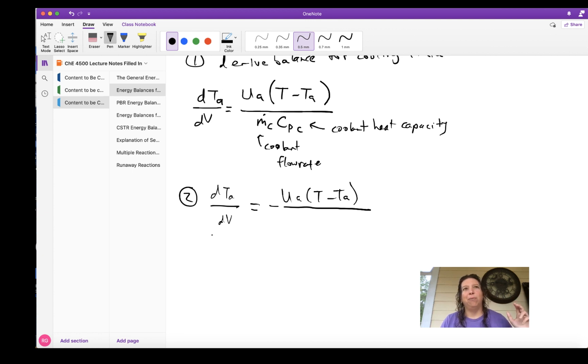So when I have my system of ODEs in the case of a non-isothermal PFR with a countercurrent heat exchanger, the balance on the cooling fluid has opposite limits of integration as the other ODEs. Rather than integrating it separately, which would mean I would lose an equation and not be able to solve it, I integrate it along with the other ODEs, but switch the limits of integration.